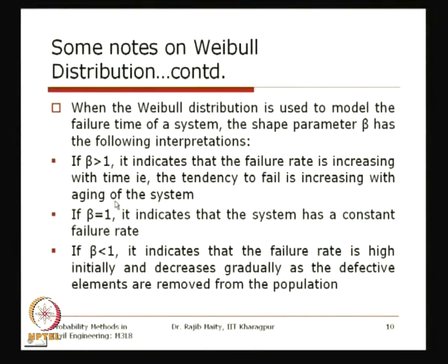So, when the rate of failure is increasing with time, that is captured when the distribution has the parameter beta greater than 1. Similarly, when some particular structural member or the structure itself, due to its aging problem, passes more time, the chances of failure increase. For those kinds of cases, the Weibull distribution with beta greater than 1 will be a suitable choice.